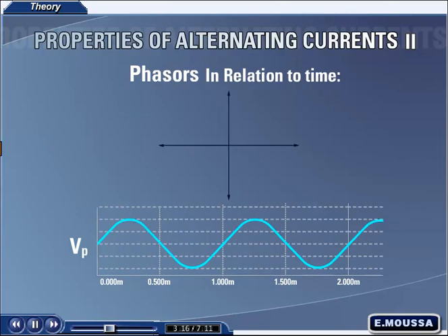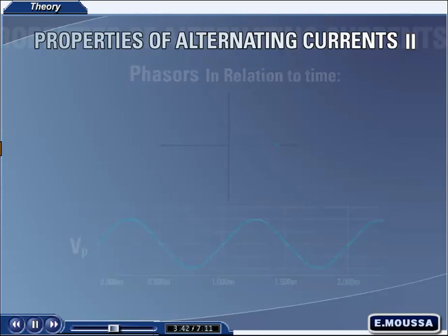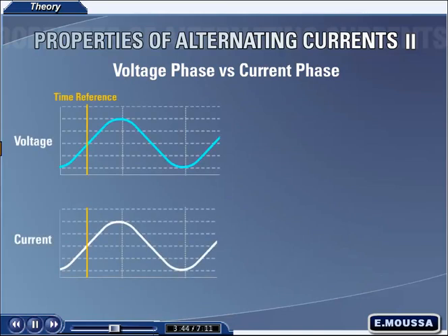For a load that is purely resistive, we could draw a vector along the positive x-axis. The voltage, Vp, isn't a vector quantity, but is represented in this manner in order to assign an angle between the voltage and current. The key is to note that the phase difference between the voltage and current is constant and will be expressed. The direction is arbitrary. For the pure resistive load, the voltage and current will be in phase. This is represented as an arrow in the positive x direction, indicating that the voltage and current are in phase.